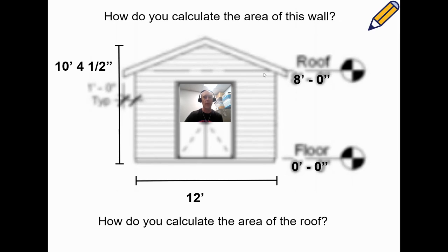And we know the width is 12. And you have geometry skills that tell you if you know the height and the width of a triangle, you can find the area. So that's how you find the area of that triangular wall part. And then we would add that to the rectangular wall part of 96 square feet. You're also going to figure out the areas of all the doors and all those pieces, and that will be part of what your work is.